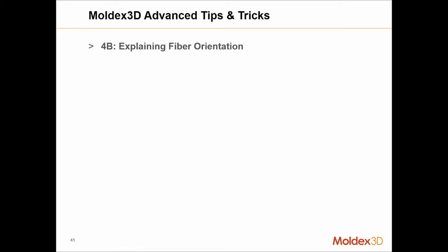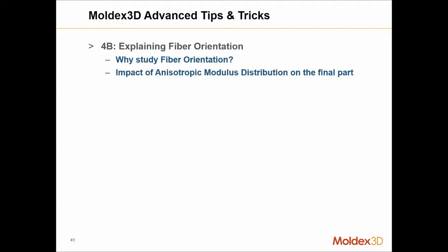In this study, we're going to ask ourselves, why do we actually study fiber orientation? We're going to discuss the impact of the anisotropic modulus distribution on the final part. And finally, we're going to use the interpretation tools in Moldex3D to interpret the fiber orientation.